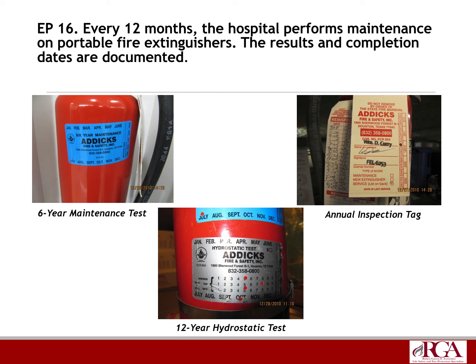So your Class K silver fire extinguisher and your CO2, your carbon dioxide fire extinguishers, need to be hydrostatically tested every 5 years. A surveyor who's savvy is going to look at your extinguishers and look for these particular service tags.